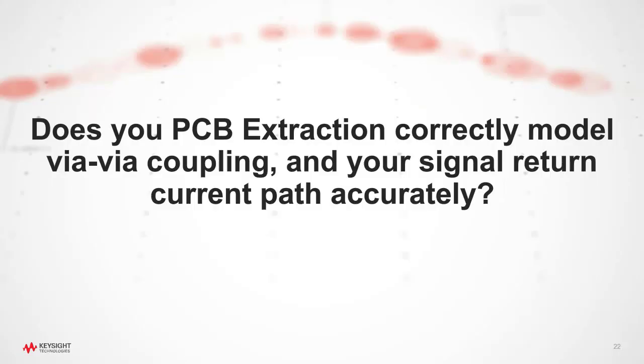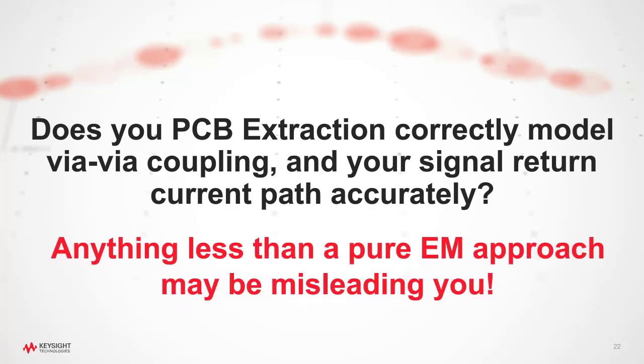This leads to another very poignant question, which is, does your PCB extraction tool today correctly model the via-to-via coupling? And does it capture the signal return current path accurately? Because, as we've shown with this, anything less than a pure EM approach may be misleading you, especially as we approach the higher speed grades of DDR4 and moving into DDR5.